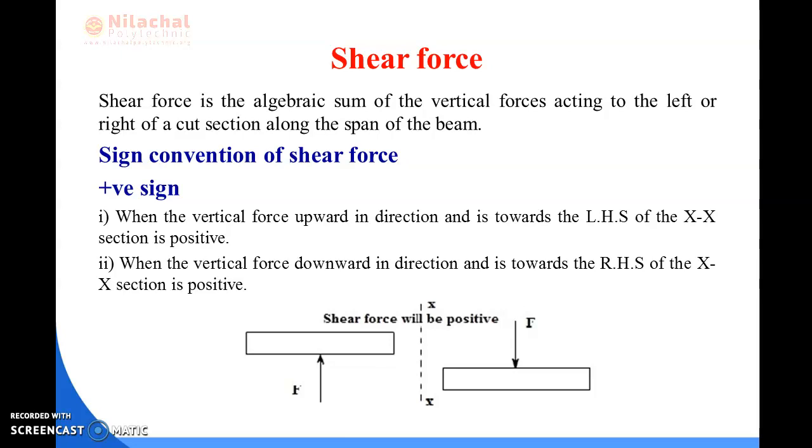That means whenever a beam is subjected to a loading system, according to your suitability you draw a cut section like XX, and then you decide on which side you consider the forces along the beam, left side or right side.